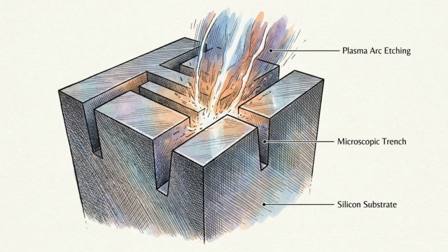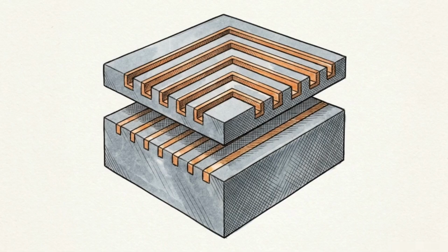Here, plasma etchers are used to physically carve into the newly exposed gaps. High-energy plasmas carve vertically through the exposed blue silicon dioxide down to the previous layer. The temporary photoresist mask is then completely dissolved. Pivoting to the addition phase, physical vapor deposition floods these newly carved trenches with conductive copper until full. The wiring is now technically embedded in the insulation.